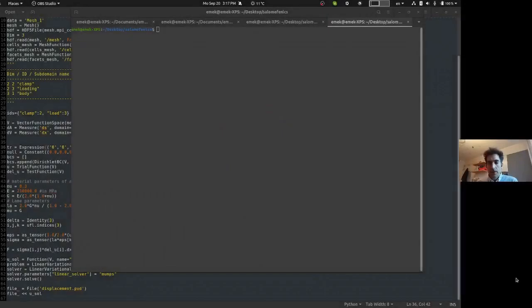So now we need to convert it to something that FEniCS can handle. There are different options, but one particularly good option is actually an H5 file, which is particularly interesting if you want to do parallel computation. If you will not, this is a really effective method of doing it. So in order to do that, we are going to use the Docker version, right? So we have this Docker. It depends on your operating system. You need to start the Docker.